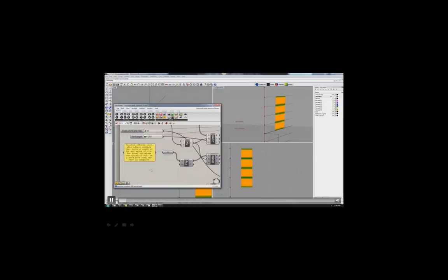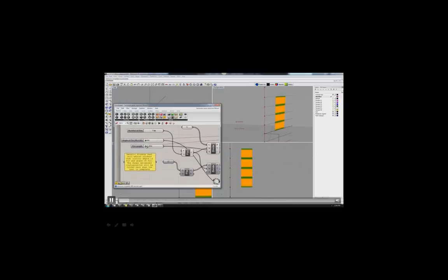All right, so what this is doing is looking at the location and dimensions of the exterior louvers for optimal shading. These sliders over here are adjusting the two variables that we've set, which are the depth and the angle of each fin. We've chosen to keep the number of fins as a constant, but you can always still make that one of your variables. And then we also set the position of the sun based on where in the world this project's located. So latitude, longitude, the specified date and time that we want to study. And then over here, we're defining fitness, which is going to be determined by the percentage exposure of the window to the sun. So the lower the number, the better the fitness, right?